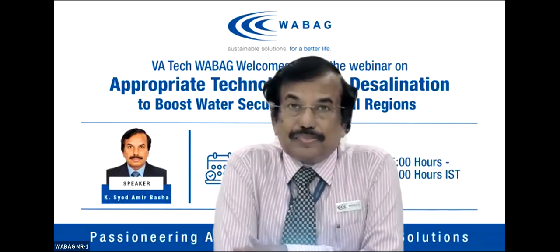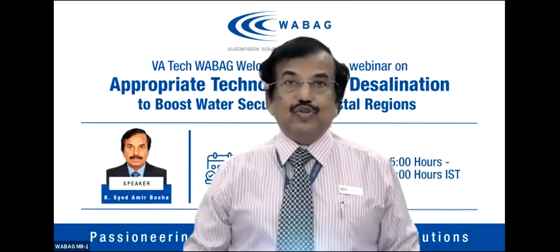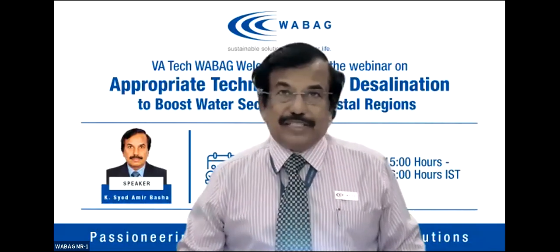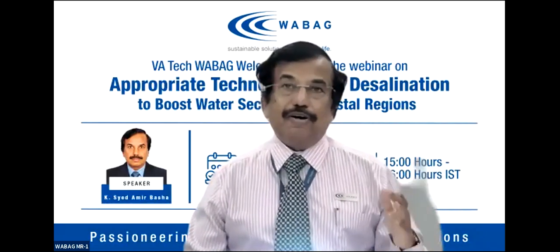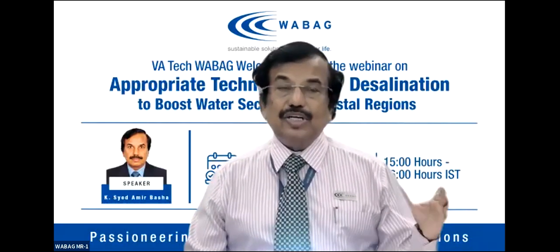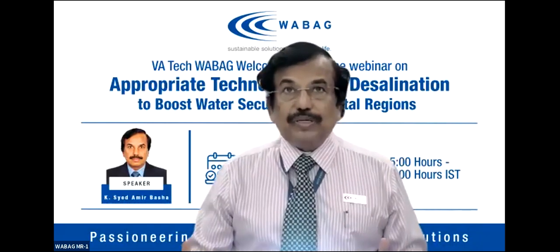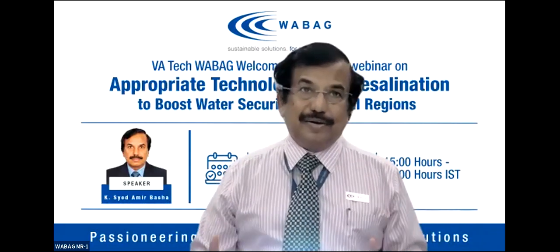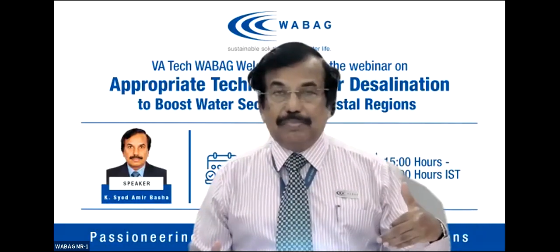The next question is from Mr. Anil Rai. What is the importance of a pilot plant for large scale SWRO projects? Pilot plants are definitely useful for a large capacity seawater reverse osmosis plant to optimize the design. For example, if you want to select dual media filters, you can go for a pilot and go in for the high flux that is possible, and so you can optimize the design. Similarly, the MF, UF and RO combination can also be run as an integrated membrane system. And then you can determine the CIP rates, the cleaning frequency to be used, and many other advantages.